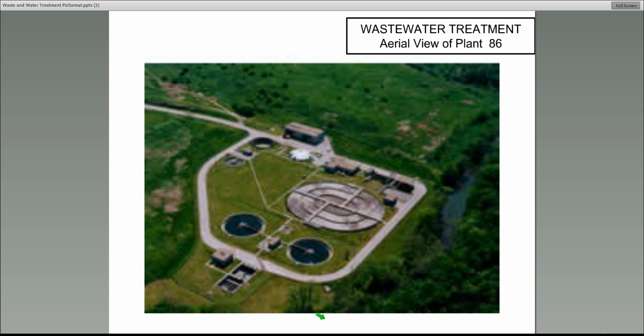Okay, first of all, the wastewater comes in above on this side of the plant, and it goes into what are called carousel or racetrack units. They're really carousel units. And if you notice, some of the units have a lot of froth on the top. Those are the aeration tanks. The ones with no froth are the settling tanks.